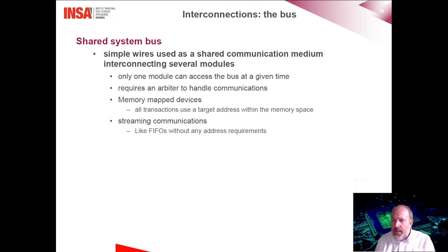You can also find streaming communication. In streaming mode, the peripherals or the IPs are not connected to the bus and communicate through dedicated components called FIFOs without any address requirements.